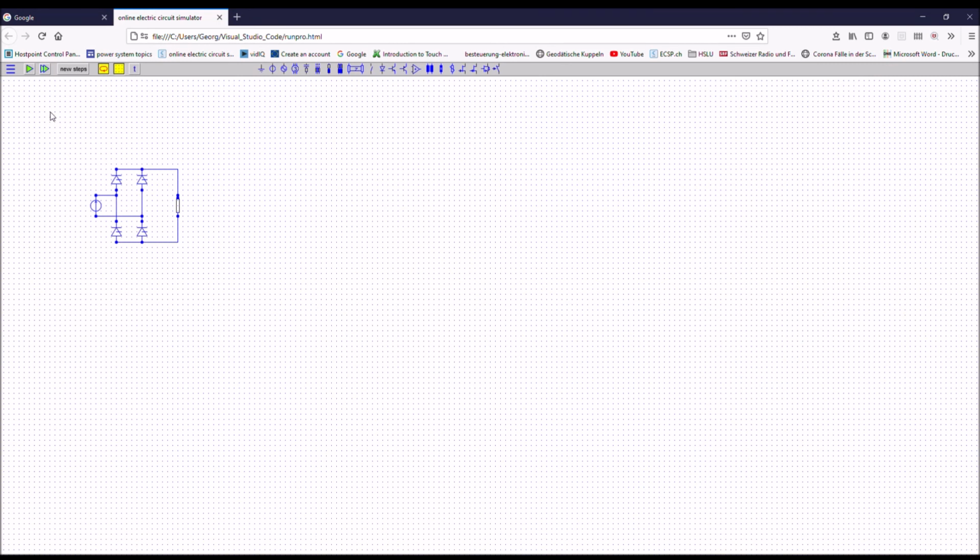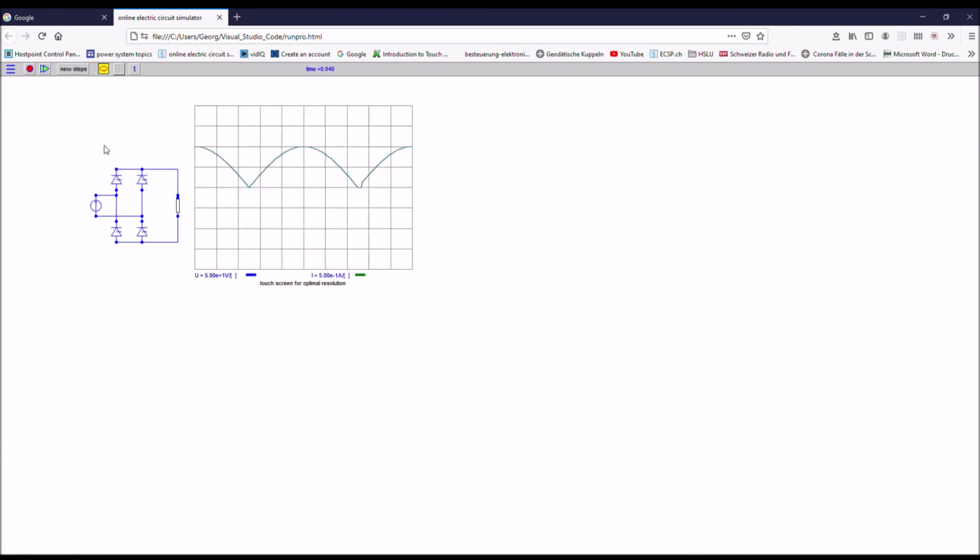To build a group of thyristors, I go to the menu bar and there thyristors group, and then I get this small window, and now I build a new group and I group these 4 thyristors all together in one group. If I have more thyristors, I could build more groups, and each individual group would then be controlled separately but by one common slider for each group. So let's now run it and let's see what happens. You remember I could control only one thyristor, but now I can control all thyristors together. And this is exactly what we wanted to see.